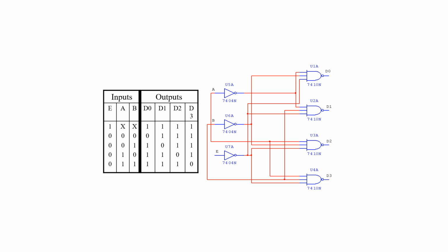It's implemented by hardware. As you can see here, whenever E equals 1, you don't care about A and B, which means A and B are your password. A and B are X and X, so there is no password to enter, and you can watch any channel as long as E equals 1. Whenever E equals 1, the decoder is giving you permission to see whatever comes on this receiver, except for the 4 restricted channels: 0111, 1011, 1101, and 1110, which are D0, D1, D2, D3.